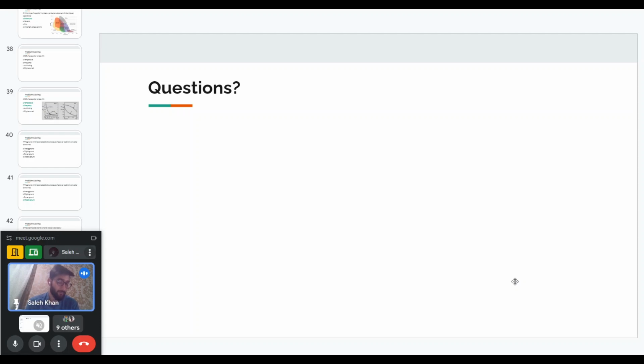You have to first design your circuit schematic, then assign a footprint to each of the components, and then place the components on your PCB and connect the different components as in the circuit. But that is a very involved process and I cannot summarize it right now, so I will refer you to the course. It is basically the very last lecture, a PCB design tutorial.